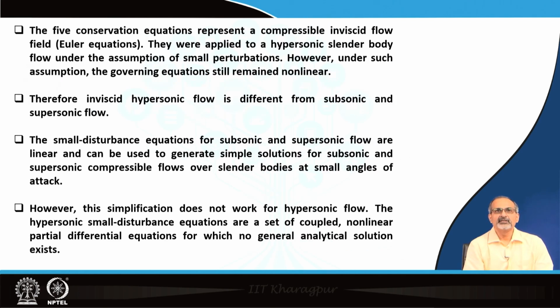The 5 conservation equations represent a compressible inviscid flow field using the Euler equations. They were applied to a hypersonic slender body flow under the assumption of small perturbations. However, the governing equations still remained non-linear.